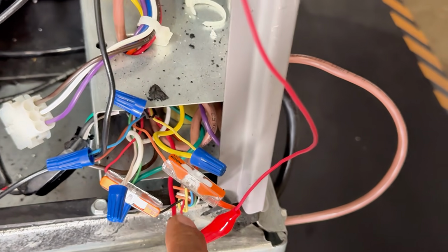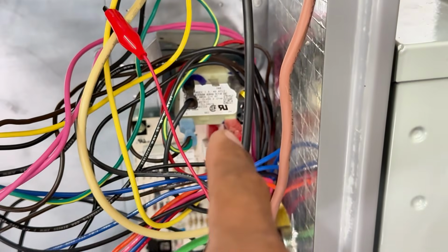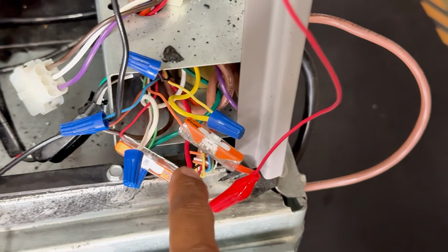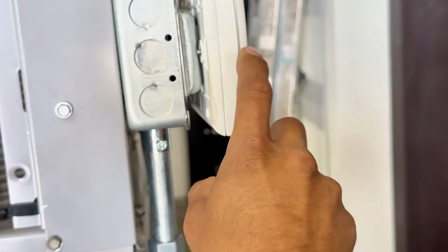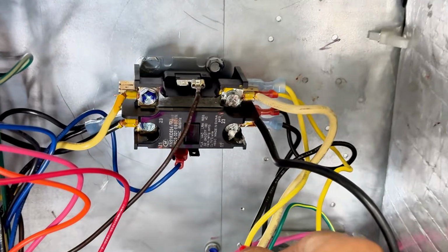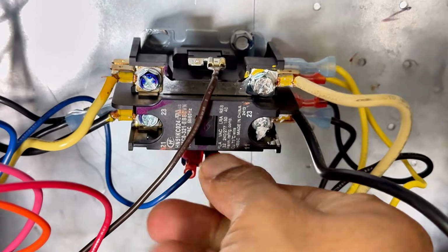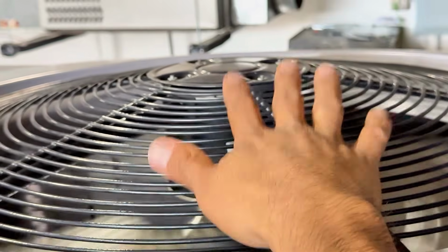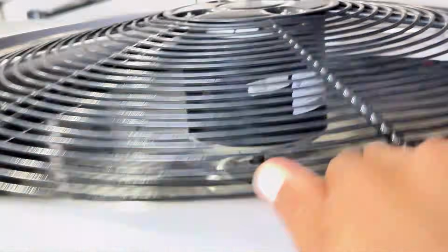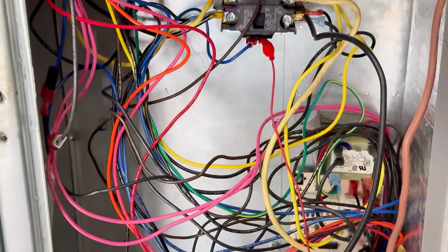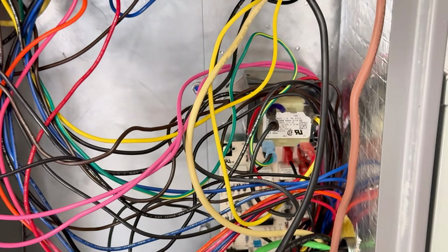And how does that look? Well, if you look down here, this is my thermostat wire. So instead of it going straight from the transformer, it's getting power from the same wire that's powering up your thermostat. Would that work? Yeah, that would work. But once again, your system's gonna stay on all the time. You saw that got pushed in. Condenser fan turned on, right? So that would work.